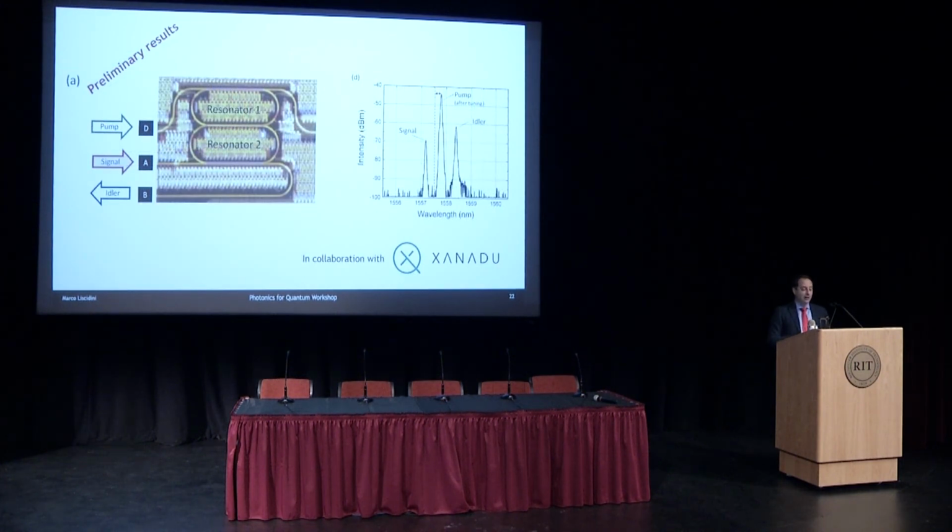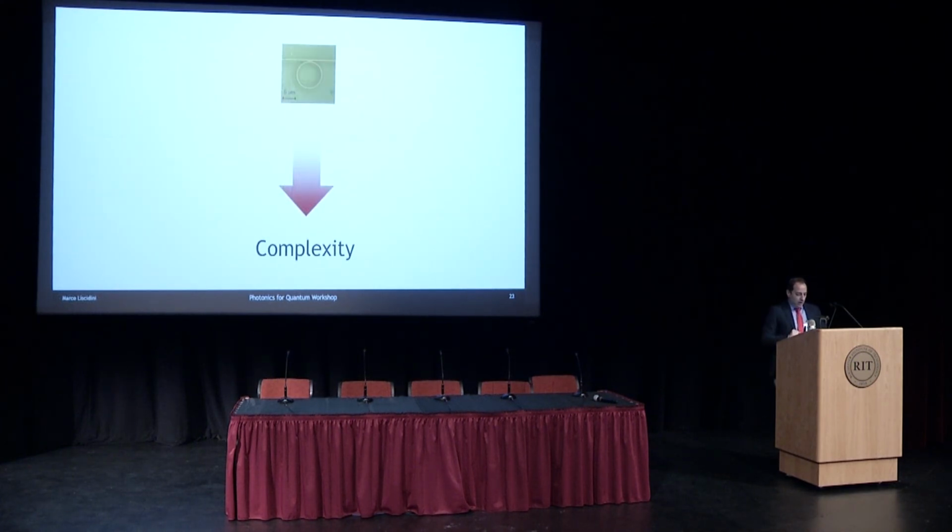Okay, does it work? Well, we have a preliminary result. We did stimulated four-wave mixing between these two resonators. We enter in this channel with the pump, and we enter in this channel with the signal, and indeed we measure an idler. This is possible only if the two resonators are nonlinearly coupled. Otherwise, it's impossible, because these three resonances do not belong to one single resonator. Two belong to this one, and the other belongs to the pump. Okay. Very good. So we moved from one single ring to two coupled rings.